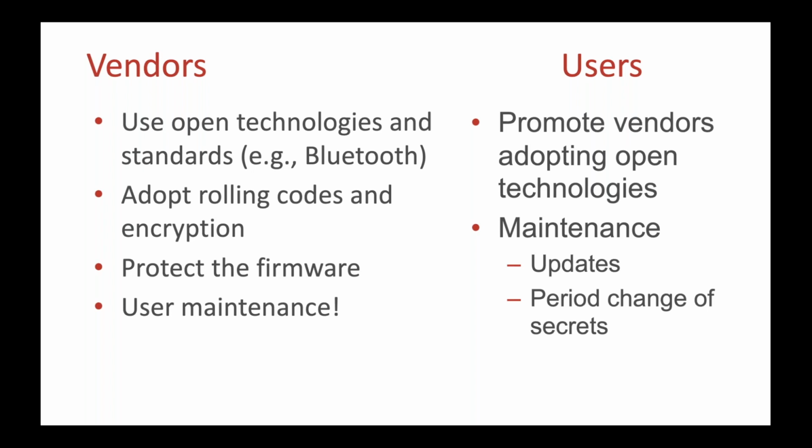In some cases, for some of the radios, so for Saga, you had to buy from Saga new crystals that match the right frequency. In the case of some vendors, there were just dip switches on the receiver and transmitter, so you just had to make the dip switches match to which frequency you were on.